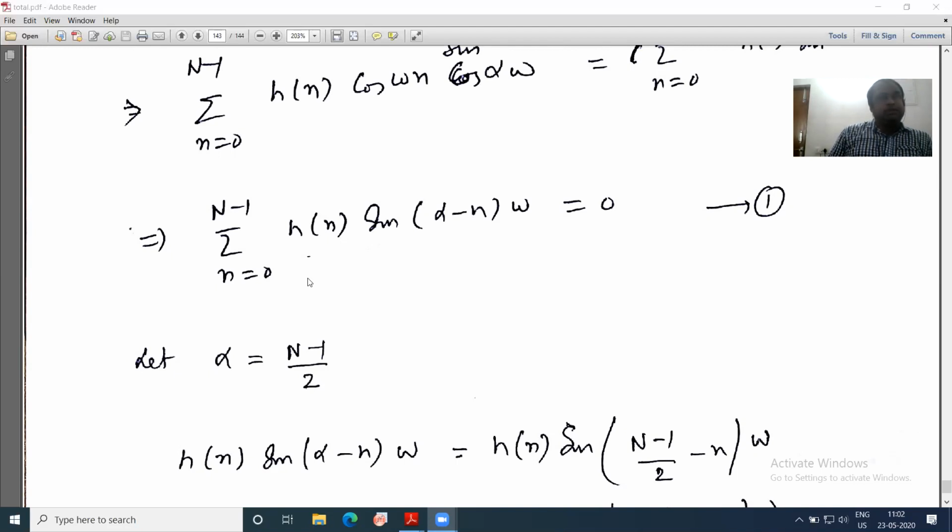Now, while extracting the desired part, it should not alter the desired part much. Suppose the signal phase is changed, then the signal will be changed. That is not desired. Whatever part we extract, that part's characteristic should not change, right? So that's why linear phase and constant amplitude are the criteria. If linear phase is not maintained, there will be phase distortion, and if constant amplitude is not maintained, there will be amplitude distortion. You have learned these things in transmission lines as well.